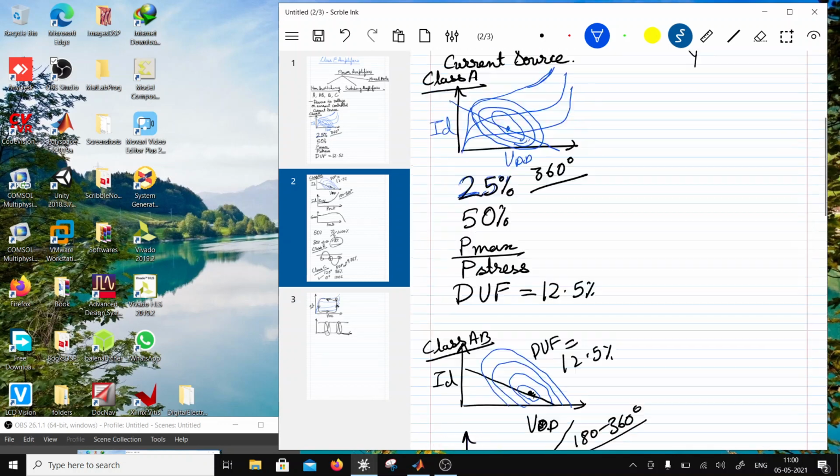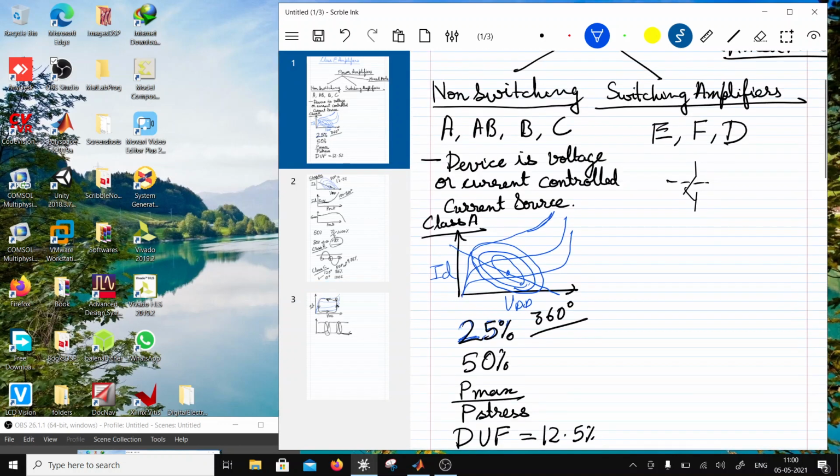Now here what's happening is I have voltage and current in quadrature. Now if I was to connect the switch across the load, I'm going to have a power delivered of 0. So in a switch the power delivered is going to be equal to 0 because the device is basically not able to put out active power. Active power means that the voltage and current are in phase.